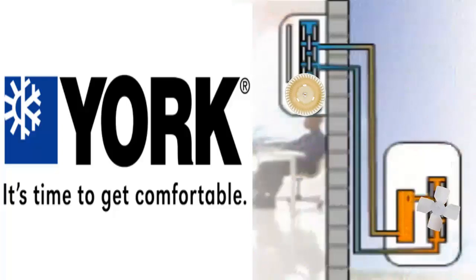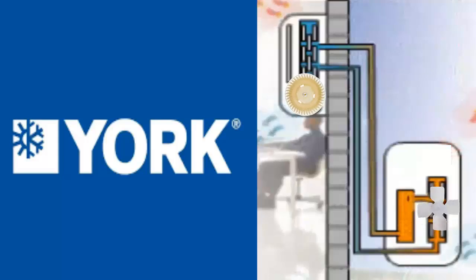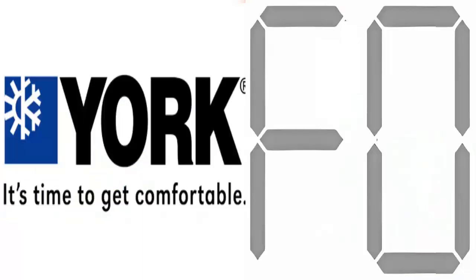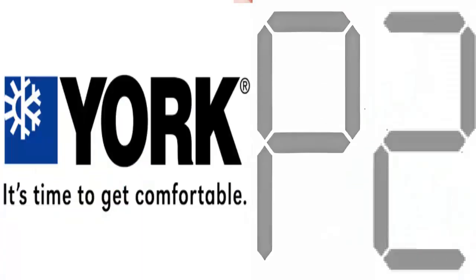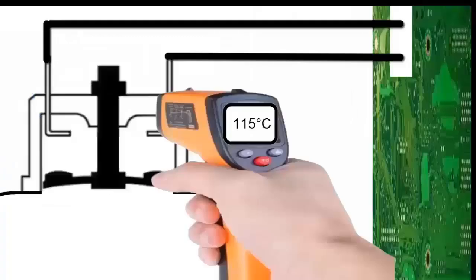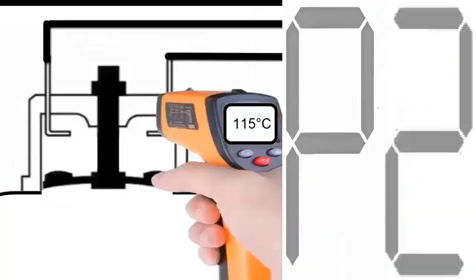In this video, we explore the faults and error codes of York air conditioners related to compressor issues. For York manufacturers, code F0 and code P2 are protections that activate when an overload in the compressor is detected.